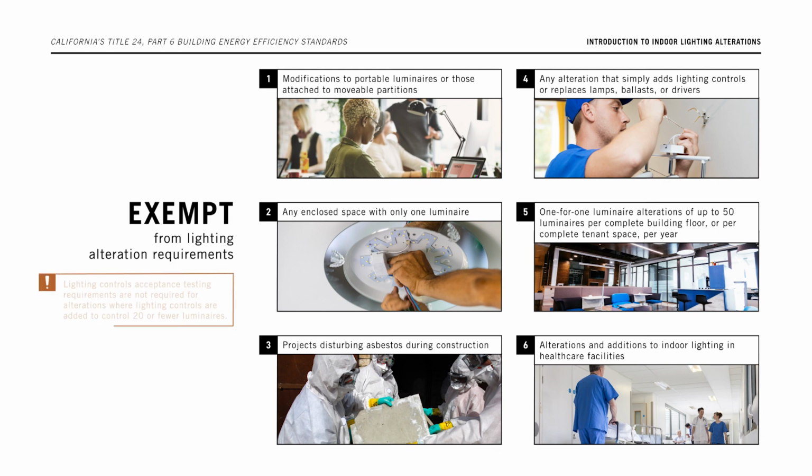On a related note, acceptance testing requirements are not required for alterations where lighting controls are added to control 20 or fewer luminaires.